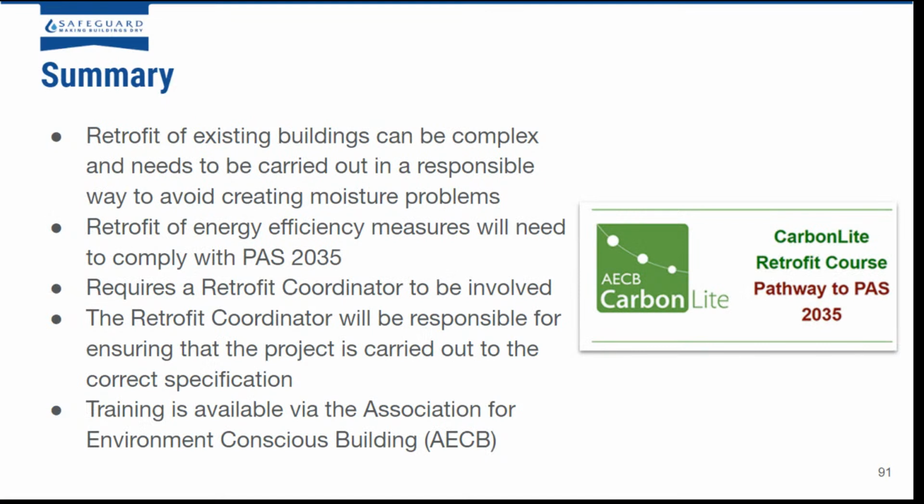Okay, so I'm just going to do a really brief summary. Basically, retrofit of existing buildings can be very complex and needs to be carried out in a responsible way to avoid creating moisture problems. So retrofit of energy efficiency measures will need to comply with PAS 2035, which requires a retrofit coordinator to be involved. And for landlords, I'd really recommend that you get involved with the Green Homes Grant, get all the grants that you can, because the minimum energy efficiency standards really are going to get harsher and harsher, particularly by 2030 or possibly by 2025, when it will have to be a C rating.